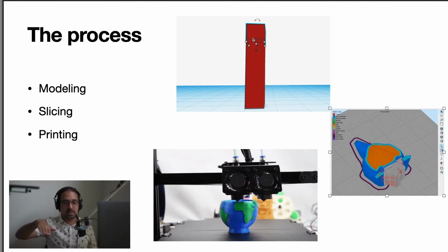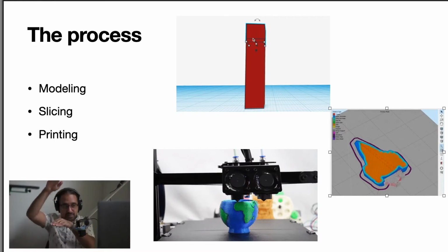So a lot of this is based on precision and strength. These different types of patterns and different percentages of what's called infill will give you different model properties. The slicing step itself used to be a lot more complicated, but nowadays it's fairly straightforward, and we'll talk about supports and rafts and what happens at the bottom of the model in a future class. I'll leave that abstracted away for now. But the important thing to remember is that the model is generated from the base of the plate and then built up in layers on top of that.